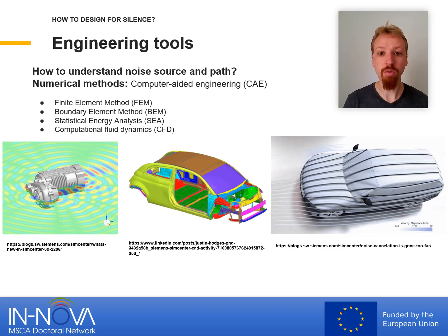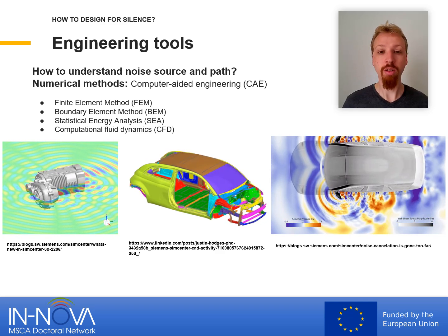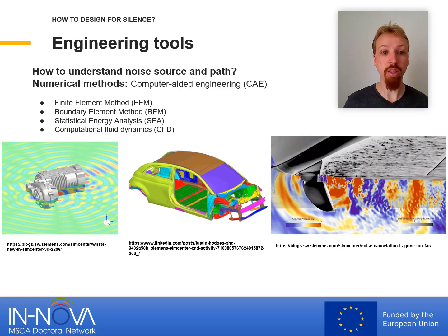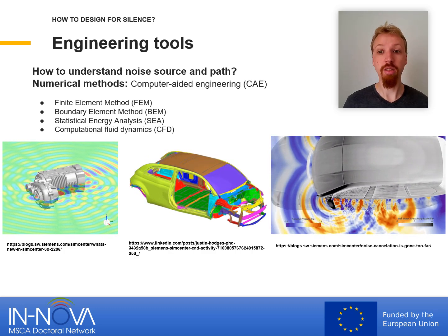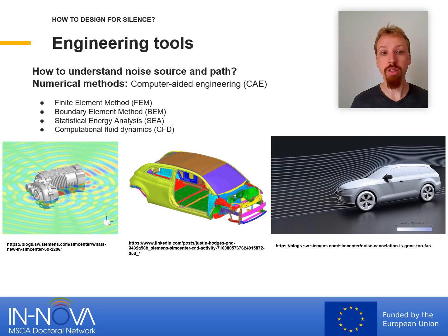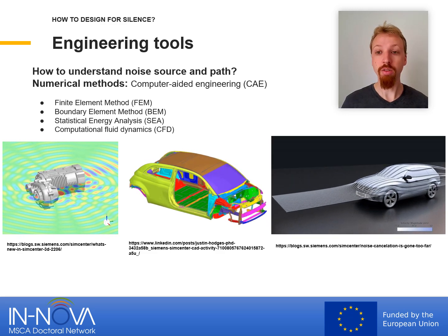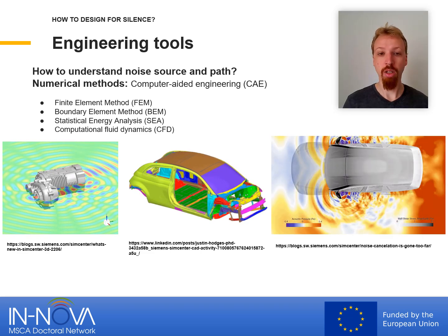With them, you can calculate the response of your structure, as in the middle figure. You see the mode shape of a vehicle body. You can calculate the radiation of your engine, for example, in a vibroacoustic analysis, or you can also do a CFD calculation to identify the aeroacoustic noise generation around the mirror of your vehicle, for example.